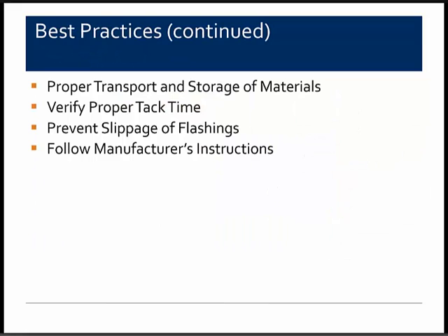You also want to make sure that the proper transport and storage of any adhesive materials is being followed. The manufacturer's labels should be read carefully. You also want to verify proper tack time between the two mating surfaces. Follow the manufacturer's instructions. You want to prevent the slippage of flashings.